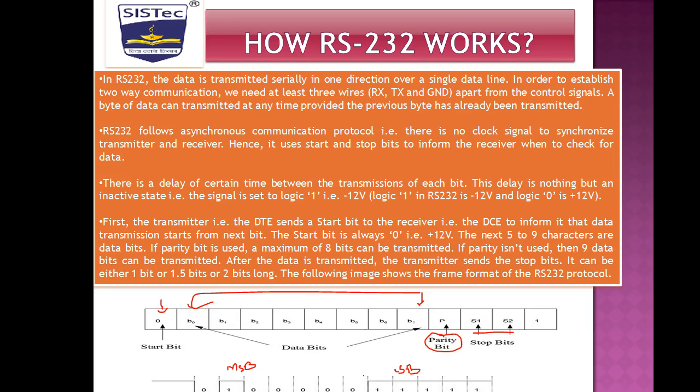When the modem connected to the sending terminal receives this carrier, it asserts Carrier Detect, that is CD, to the terminal. After a proper time interval, the modem sends Clear To Send, that is the CTS signal, which indicates the modem and communication channels are ready for transmission.